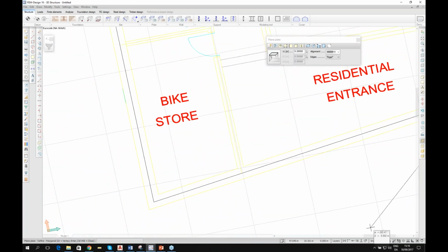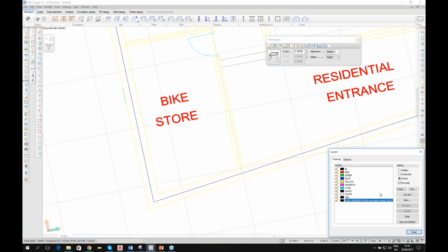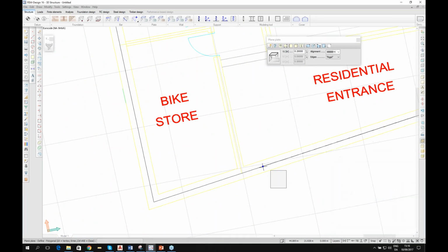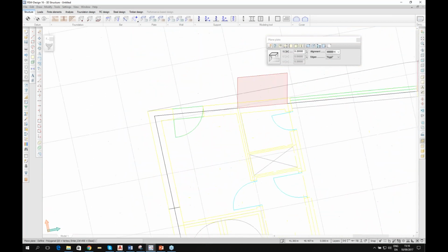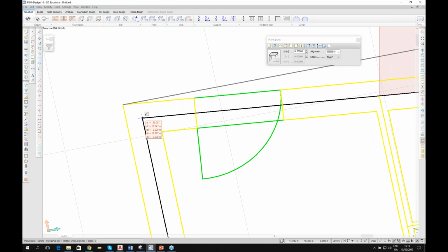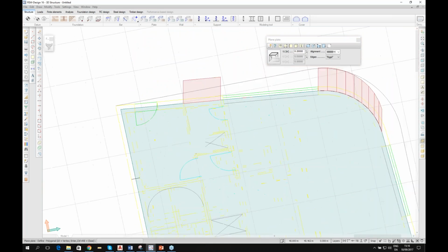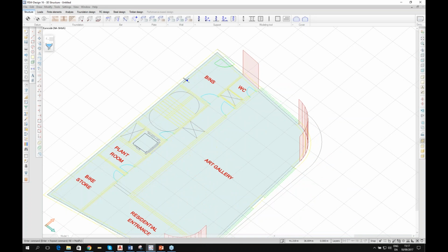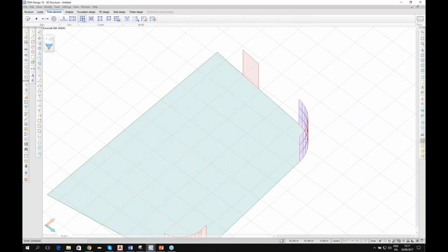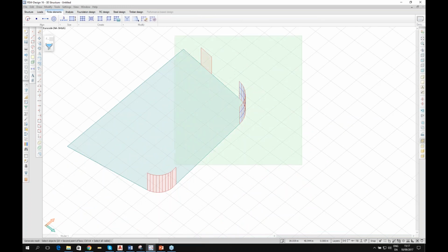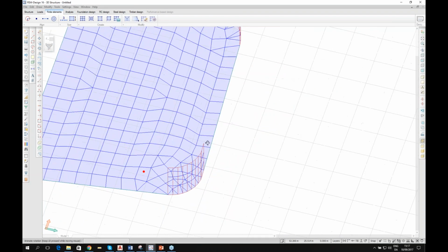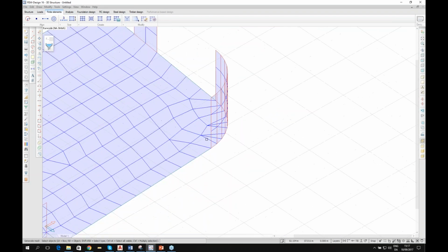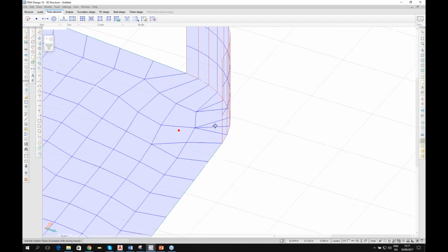Now I want to go back and snap to my drawing. So I deactivate the no snap in my layers. And I have my plate. Again, I check with my finite elements by generating a mesh. Just select my elements. And now I see I don't have a warning. So this is good. I have a proper connection between my plate and my walls, and my mesh looks good.